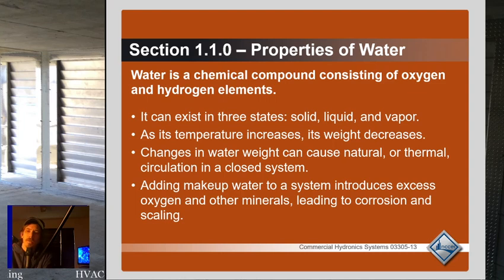So, older steam systems didn't have circulator pumps, right? I think they did it with hydronics too, but I can't remember a specific example. Steam systems don't have pumps really anyway, except for on the condensate side, but you would have like one pipe steam systems and things like that, and basically the steam rises and then the condensate drains by gravity back to the rest of the system.